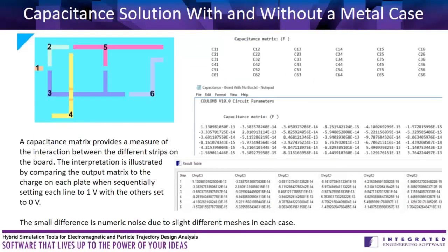So a way to understand this more completely, the kind of onboard interactions that's subject to different kinds of geometry, will be to look at this not as a fields problem, in which case you need to keep assigning one thing and then another and examining what you've got, but to look at it as a capacitance problem. I've labeled here, using the same numbers as I gave the lines in the model, 1 to 6, the different lines, all of which may in general be at different voltages.